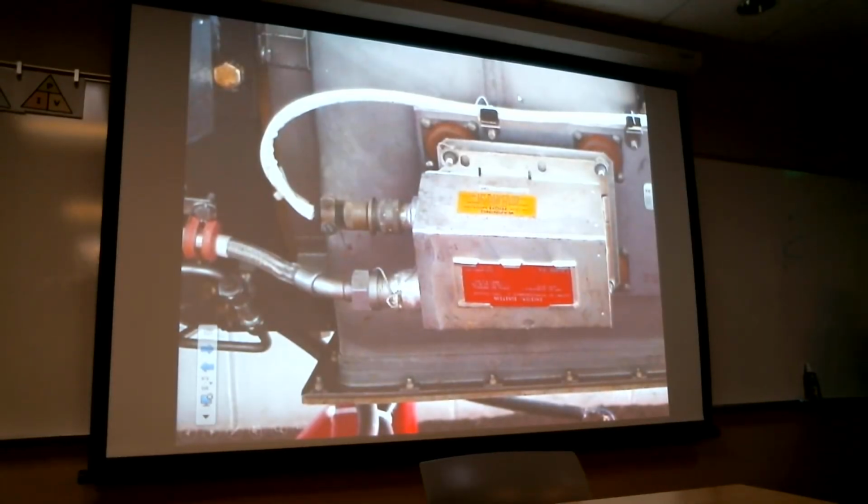So here's a ship's mounted installation. How many channels is this, would you guess? One. Single channel, one power wire from the aircraft. You've got the box, it's mounted in this case on an APU duct. So these things take on all kinds of different appearances, but they all kind of look the same. Typically, you've got a data plate on them that will say ignition exciter, which is going to give you the lead in as to what it really is.